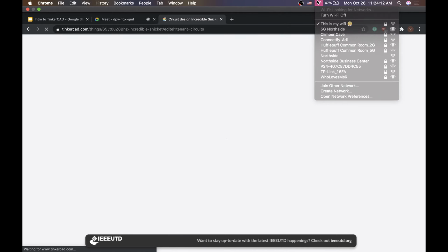All right. So I'm gonna continue. So there's 3 pins for the temperature sensor. I'll try to go a little slow since there's apparently a little buffer with me streaming. But the three pins are: the leftmost is power, the middle one is V out, and the right side is ground. So what we're gonna do is wire it exactly like that.